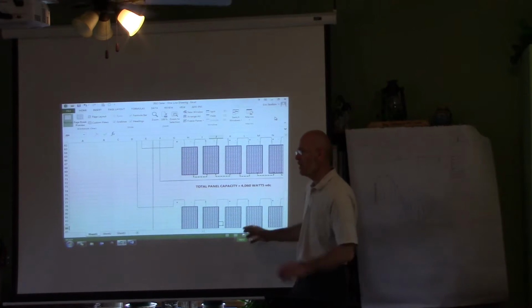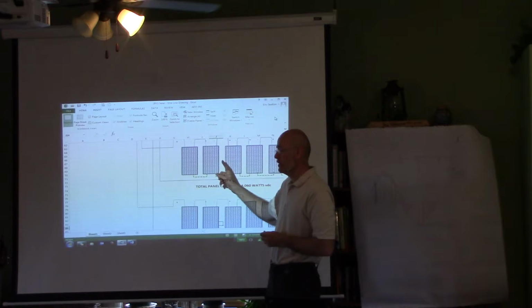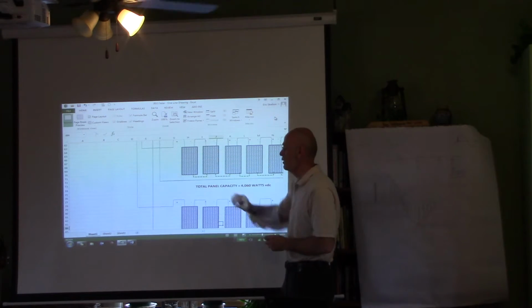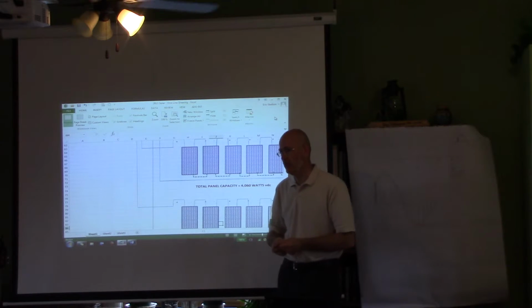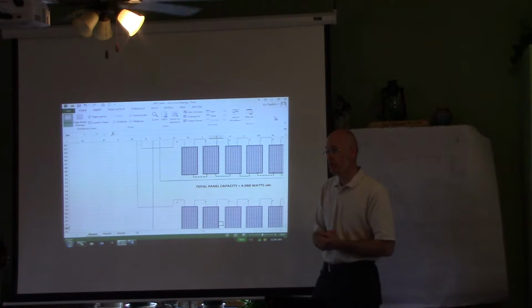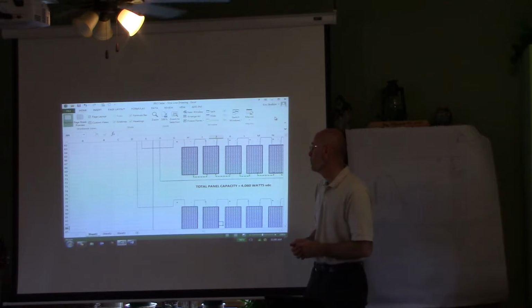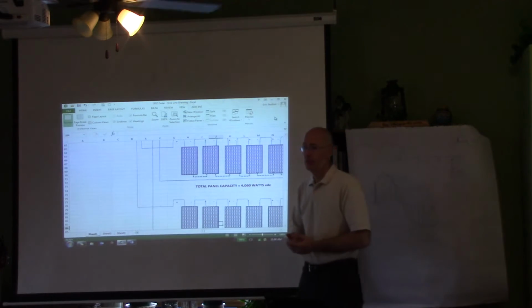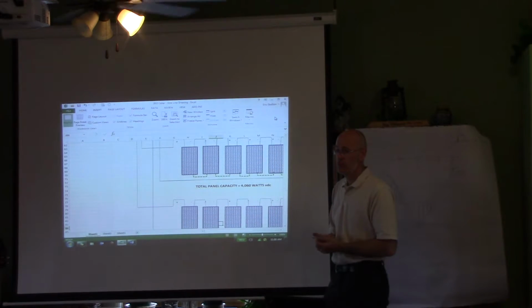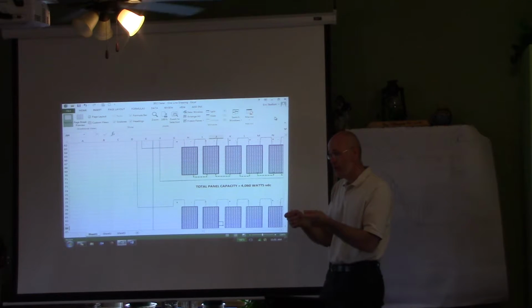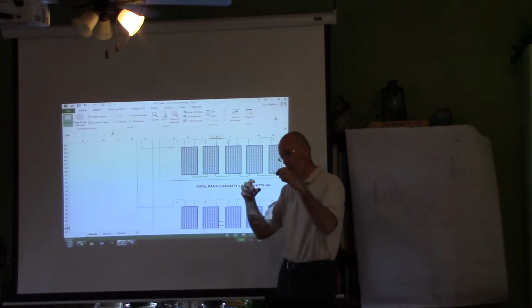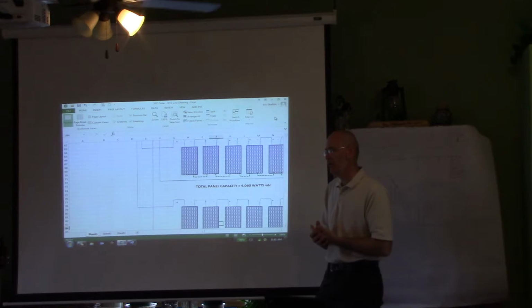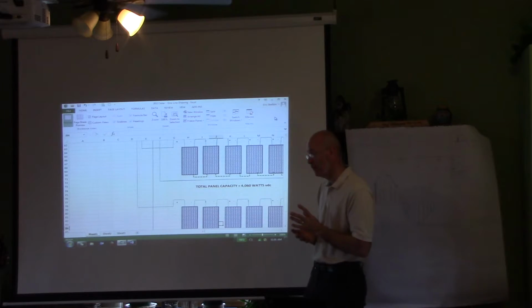Once you guys start building this rack out in the backyard, you have to think, oh, okay, the rack's up, we're going to mount the panel. Mount the panel. There's 2 wires coming off the panel. Is there voltage on those wires? Yeah. It's in the sun, there's voltage on those wires, and you can check it. Now I start hooking them together. Oh, what's the voltage between here and here? 270 volts. If you touch those wires, you're gonna really feel it. They're insulated, they're made so you can handle them, and the wire isn't exposed. They're sort of hidden shell pin kind of thing. So it's safe, but you gotta be careful too.